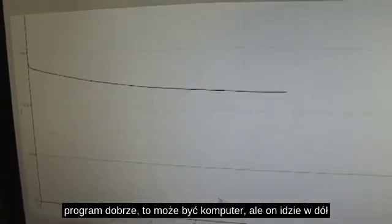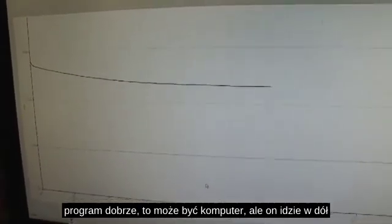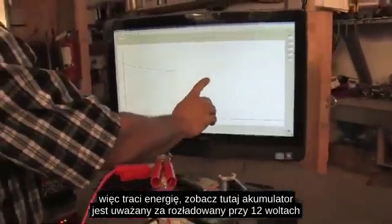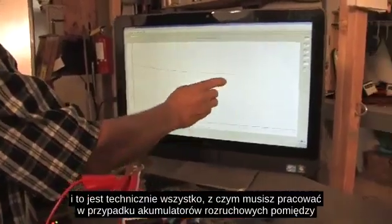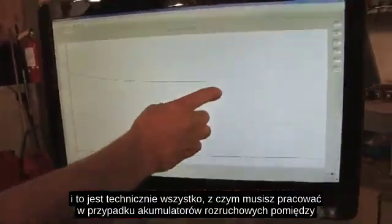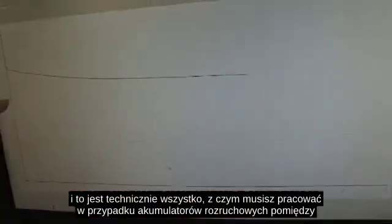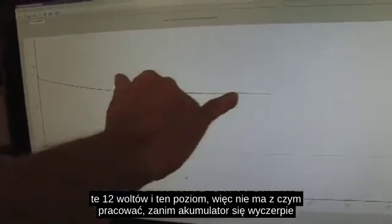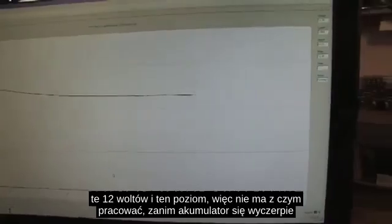Well, it could be, it could be the computer, but it's stepping downward. So it's losing energy. See here, the battery is considered dead at 12 volts. And this is actually technically all you have to work with on starting batteries, between this 12 volts and this level. So it's not very much to work with before your battery's dead.